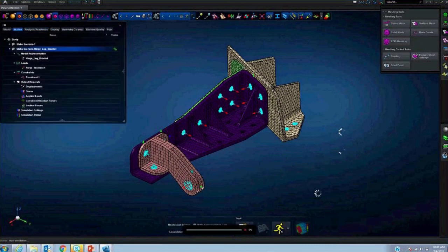So what did the script do basically? It did create tet mesh for this left bracket, and it did create tet mesh for the rest of the bracket, and it did constrain certain areas here, and it did create the fasteners between these parts. A macro record can create one of the fasteners, and then through a CSV file, we can read in the connector locations and also the parts to be connected information.